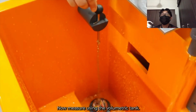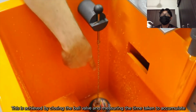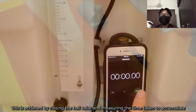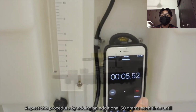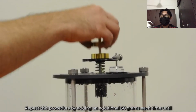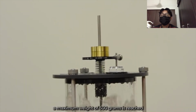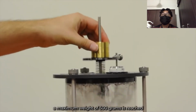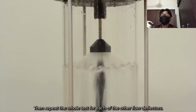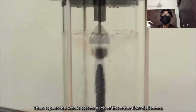Now measure using the volumetric tank. This is achieved by closing the ball valve and measuring the time taken to accumulate a known volume of fluid in the tank, as measured from the side glass. Repeat this procedure by adding an additional 50 grams each time until a maximum weight is reached. Then repeat the whole test for each of the other flow deflectors.